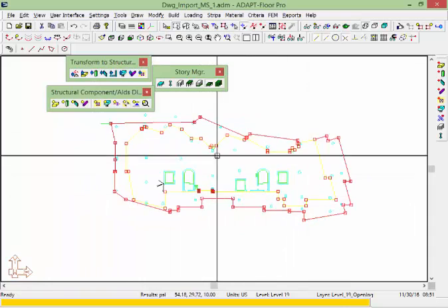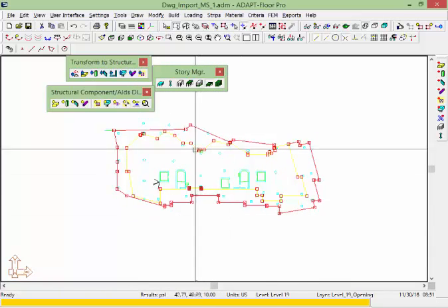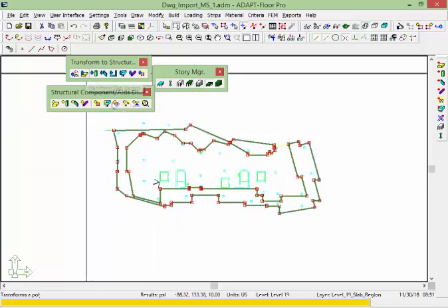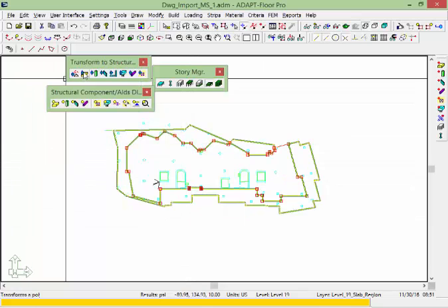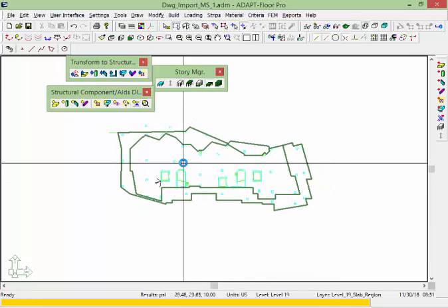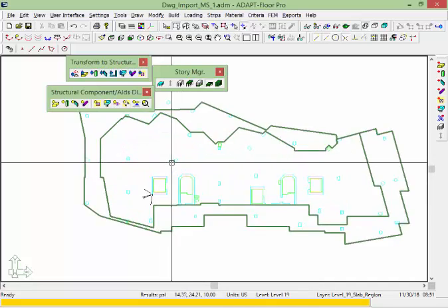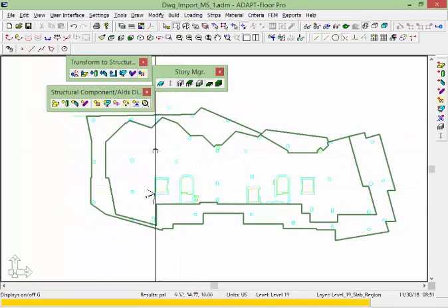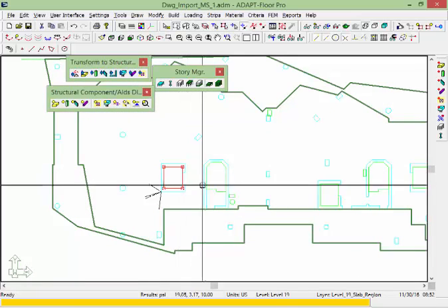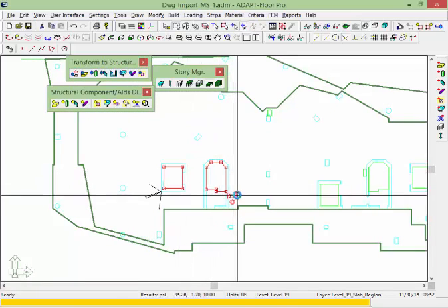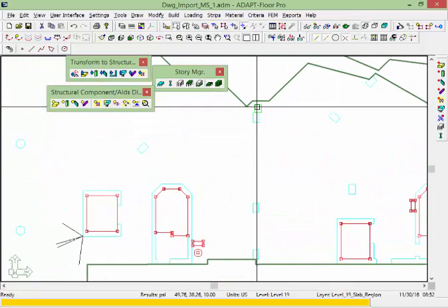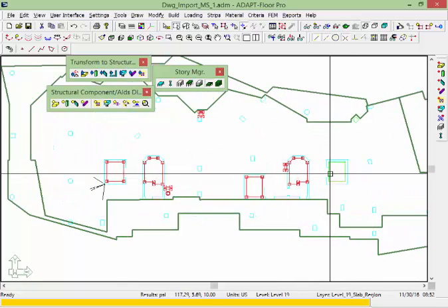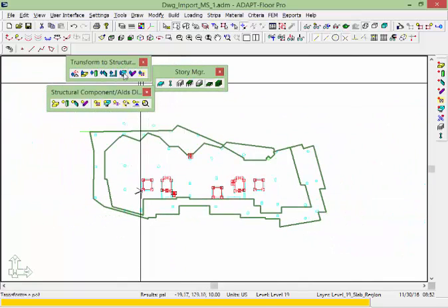and now we're going to begin modeling the slabs. So in this case we're just going to model the slabs as they've been brought in. We'll go ahead and transform that slab, and then we also have an inner slab here that we're going to transform. We'll just assume they're the same thickness. The user can adjust the thicknesses as I showed earlier, and we're also going to now do the openings. So we'll select our openings again, and here we have another opening up there near that column,